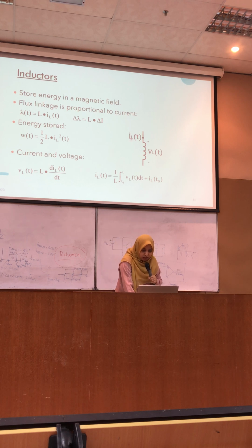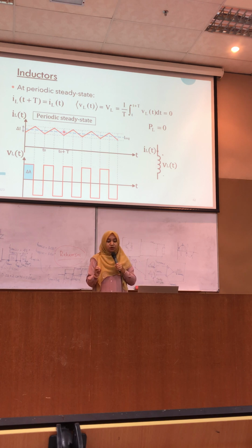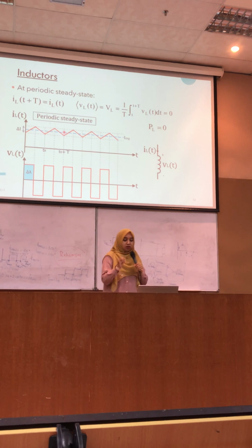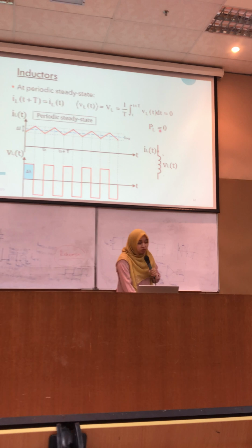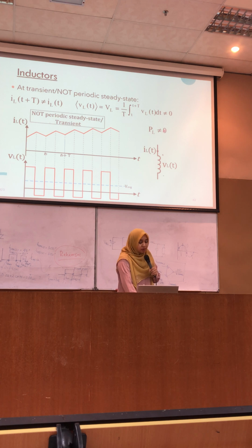Again, the inductor is a current element component. This is the inductor current waveform. If it is a periodic or steady state waveform, the average power for the inductor will be equal to 0, same as the capacitor. If it is non-periodic, it will not equal 0.